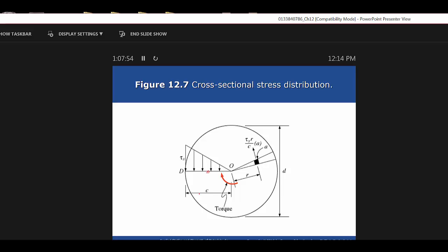The inner diameter. That is the inner surface. So it's 8,050 divided by 2, because the 2 is half of the 4, isn't it? So there's 4,025 psi max shear stress going on the inside of that pipe.